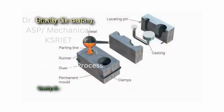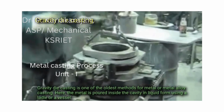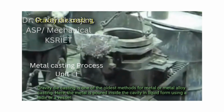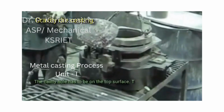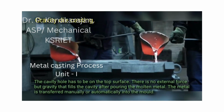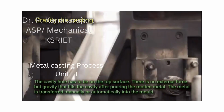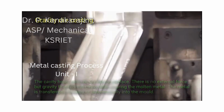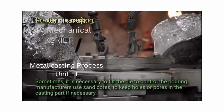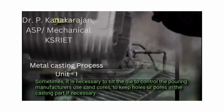Gravity die casting. Gravity die casting is one of the oldest methods for metal or metal alloy casting. Here, the metal is poured inside the cavity in liquid form using a ladle or a vessel. The cavity hole has to be on the top surface. There is no external force, but gravity that fills the cavity after pouring the molten metal. The metal is transferred manually or automatically into the mold. Sometimes it is necessary to tilt the die to control the pouring. Manufacturers use sand cores to keep holes or pores in the casting part if necessary.